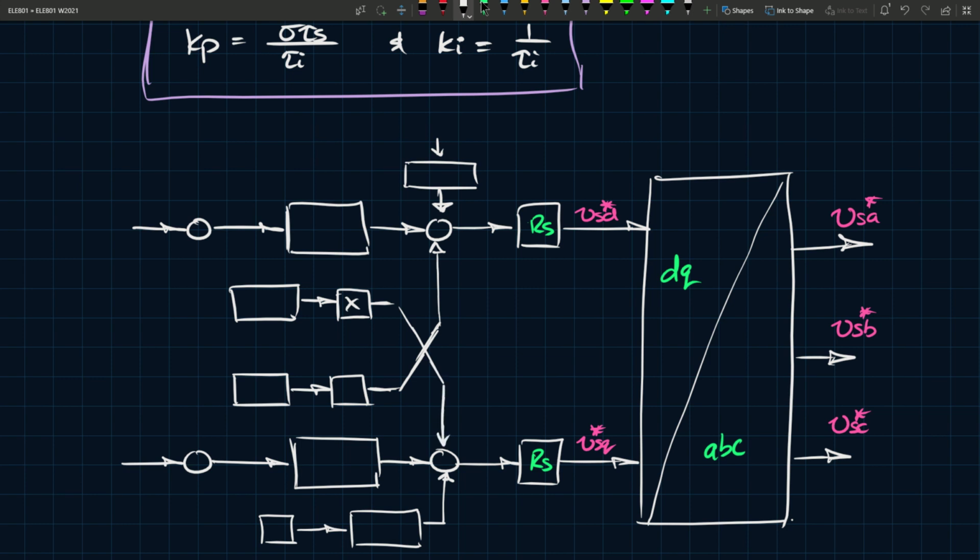By adding from one side and subtracting on the other, you can basically use what they call feed forward in order to nullify the effect of one variable on the other. So in the middle here we have omega, and omega comes in like this, and omega multiplies with both of these. So why don't we call this omega? And then omega also goes down like this and multiplies. I'm going to run out of space, but that's okay.